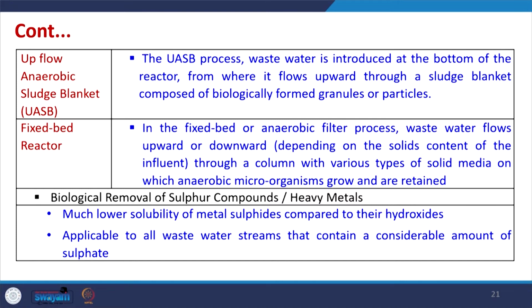Now, upflow anaerobic sludge blanket reactor is similar. It is very common. It is commonly called as UASB reactor. So, in the UASB process, wastewater is introduced at the bottom of the reactor, from which it flows upwards through a sludge blanket.